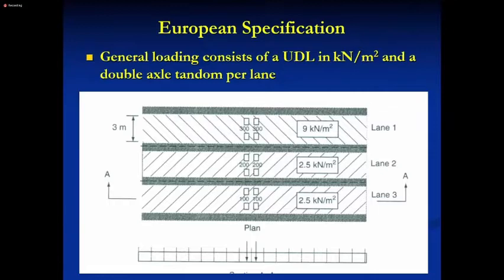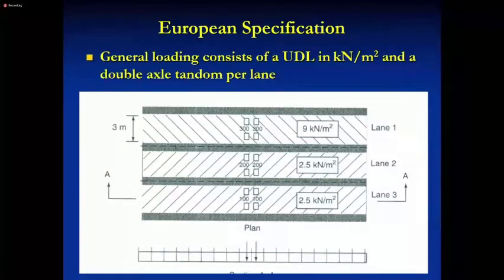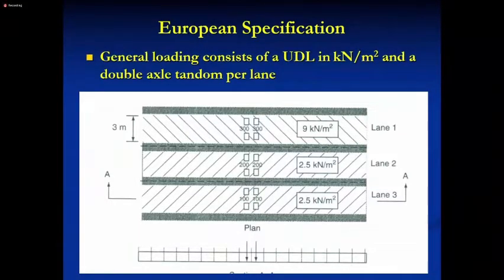Otherwise, in my case, I generally look at the most critical and apply those critical ones and get the bending moment diagram. So people spent a lot of time finding the bending moment due to highway loading earlier, but now all the software has automated it. Midas Civil can generate the envelope. CSI Bridge also can generate it. But Midas Civil is more popular among big engineers.